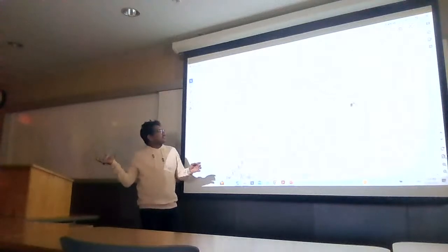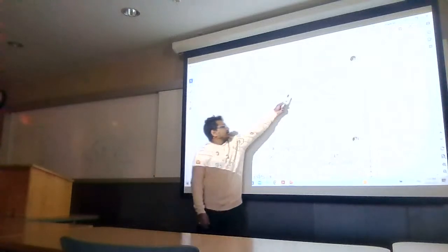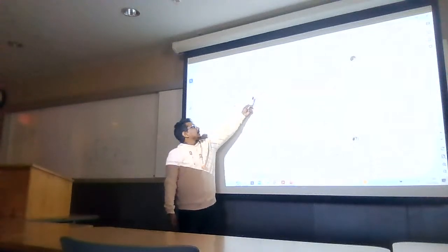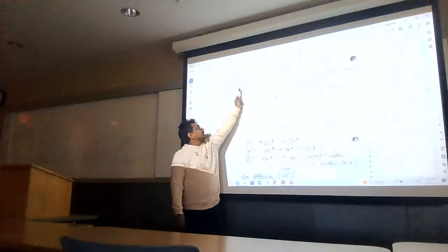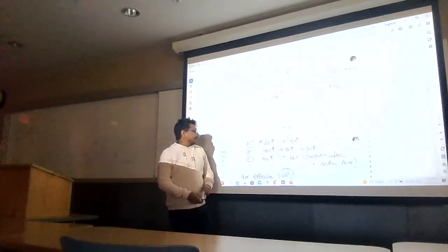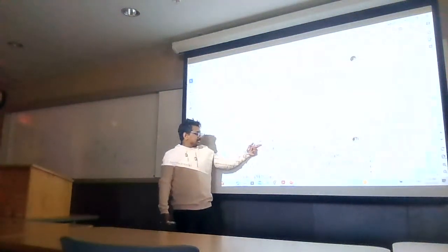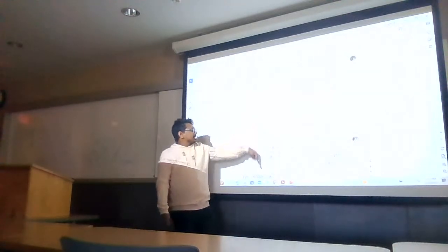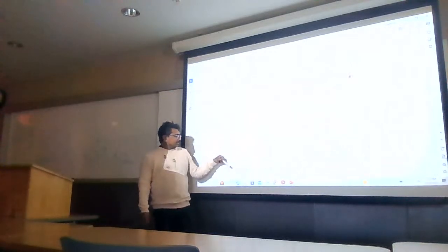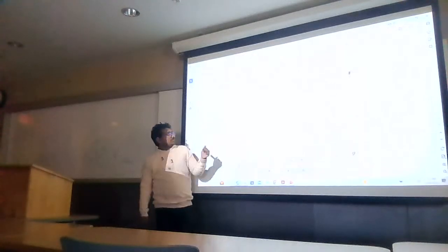Okay, go a little bit up. Yeah, these are the 3 important graphs. These 2 graphs we already discussed. There is another relationship between GM and ID: as I explained, if we need higher GM, we have to increase the ID. This is the ID versus GM curve, where you can see that if we want more GM, we need to increase ID. There is some basic relationship. I can also provide this slide or PDF. You can collect it. Can you go down? There are some expressions.